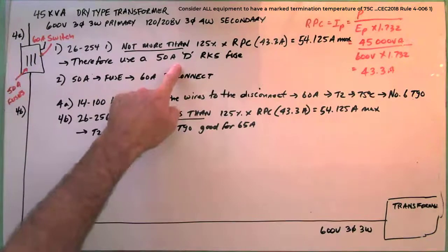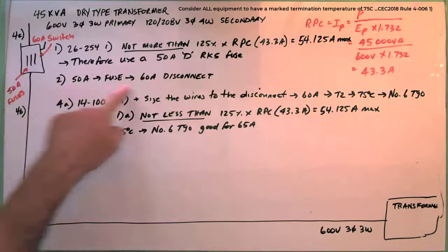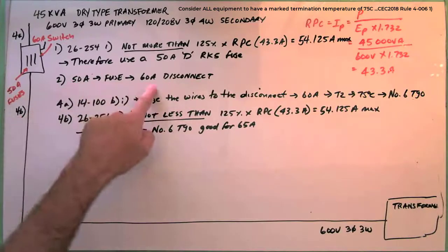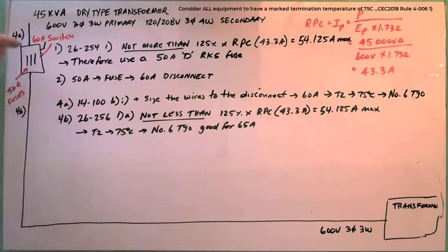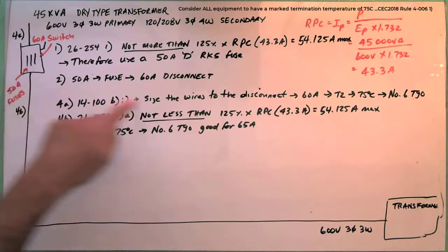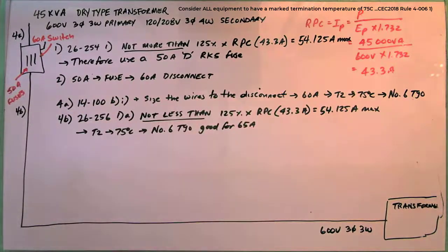But once you figured out what fuse size you're going to put, what disconnect do you need? I gave you this chart, right? Good. And then what's the wire that I need to put for this switch? Rated for the disconnect. In a general location, they want you to rate the wires for the disconnect. Are there other options? Yes. Electrical is forever, guys. You can do a lot of different things out there. If the fuse over here feeding into this, let's say it's a non-fusible, well, those wires could be anything coming in here. It's size protected by some overcurrent device ahead of this switch.